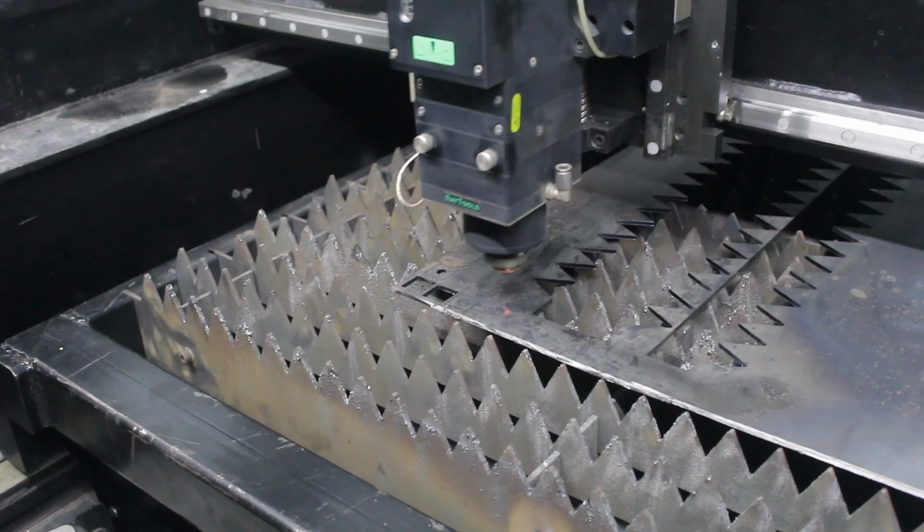The servo motor must produce enough torque to move the load, in our case the laser cutting machine head, moving plate and ball nut weight, and also accelerate all the rotating components and maintain stable control without vibrations and overshoot. That's why inertia calculation is essential.